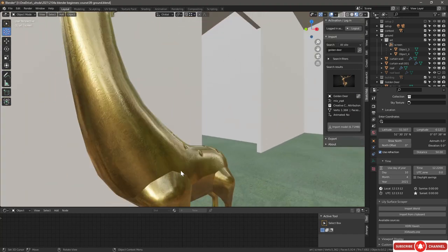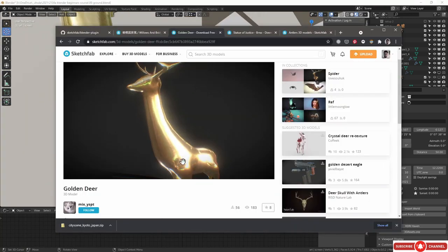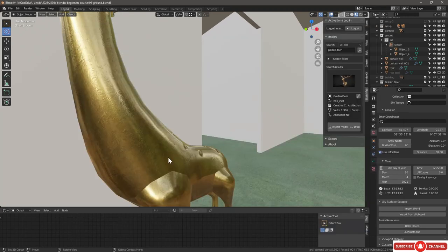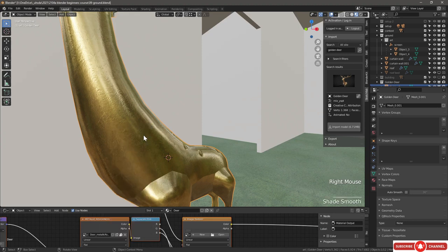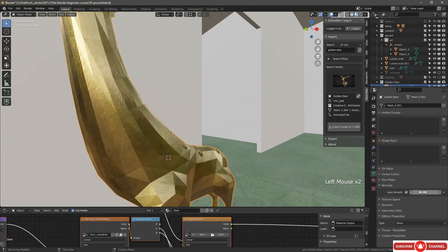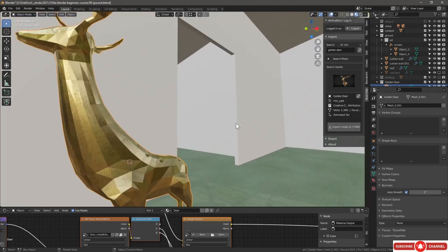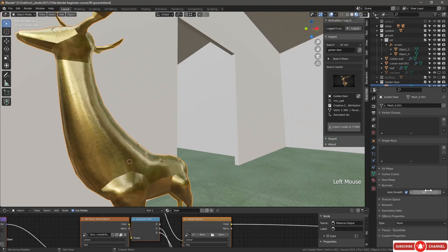I think there's some sort of issue here with the normals. Let's check how it looks here, whether it's meant to be that way or not. And it isn't. So we need to change a few settings. So if we select our object, right click, shade smooth, and then auto smooth, and change the angle to something small like 2. Oh, that's different. We can keep it as triangulated as well. Or we actually make it larger, so maybe like 60.